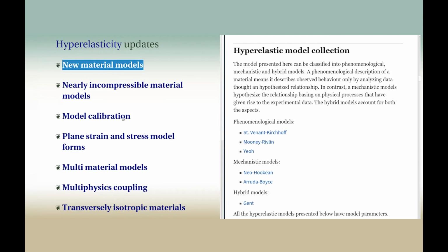We've added sections on model calibration. So typically for people that do hyperelastic material models, they have experimental data and they need to fit their hyperelastic model to this data. This is something we're particularly proud of because it's dead simple now to do this in the Wolfram Language in Mathematica, because fitting material data is so easy, and we've made it so that these components, like fitting the data and the model calibration, work very well together. Hyperelastic models are now available for plane strain and plane stress models, multi-material models. So this is maybe another thing to look at.